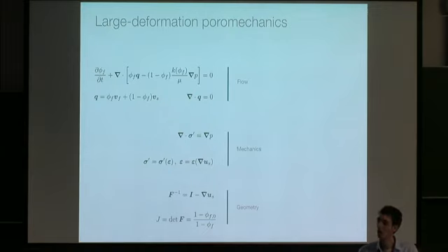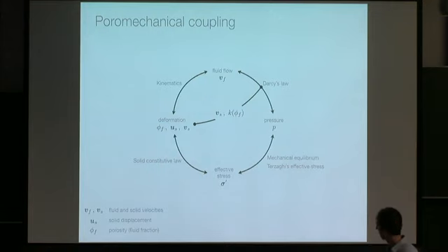Does the density of fluid become like the porosity of fluid, in a sense? The density of fluid is constant, I'm assuming. The porosity is the volume fraction of fluid locally. So at a point in my material, how much of that volume is fluid versus solid. The porosity can change, but the density cannot. Total porosity has to stay the same, yeah? Yes, that's right. If you have some sort of porous material in a box, you can't change the total porosity of what's in your box, but you can change the local values by rearranging. Yeah, exactly. Okay, so I have this picture again.